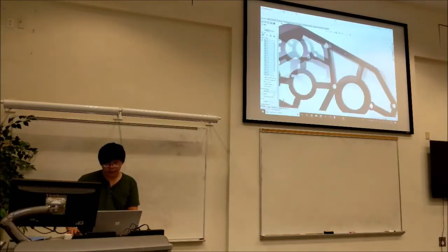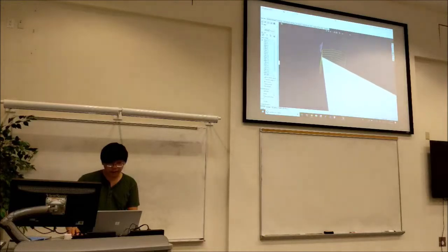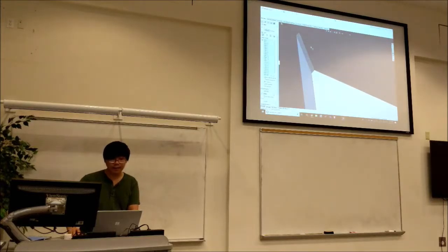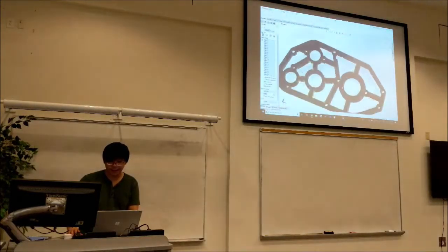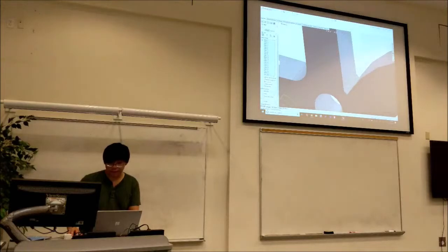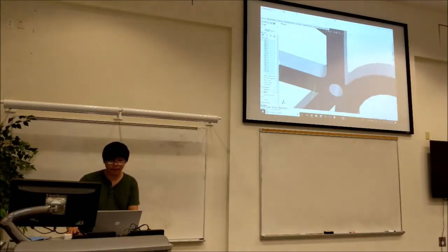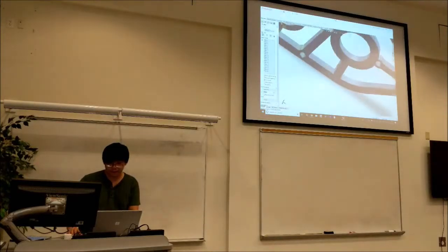And then here, you have that issue where, you see, you don't really want that on your fillet, so you're gonna have to face fillet it later. You can also fix this at the sketch level, but that's just really time consuming. So I just go ahead and do this, even though it's technically not as good practice since you have so many features in your part, but.